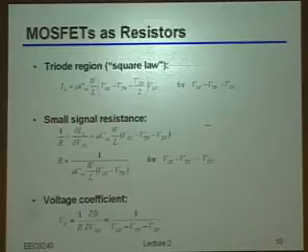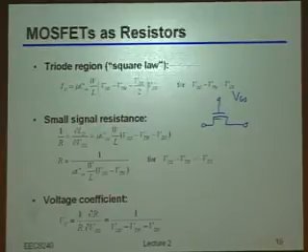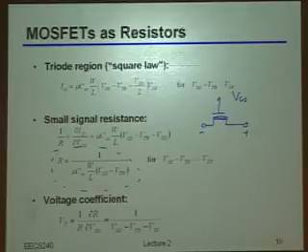And again, hopefully the idea here is fairly obvious in that, if you took a transistor and you biased it with a high enough VGS, basically it's looking like it's in the triode or linear region, such that, of course, the channel charge is relatively flat underneath there. Indeed, it looks essentially just like a resistance, right? So if I look at the resistance across these two terminals, you can get one of these classic types of equations here, which really just says that it's a resistor with some dependence upon what the VGS minus VT actually is, okay?